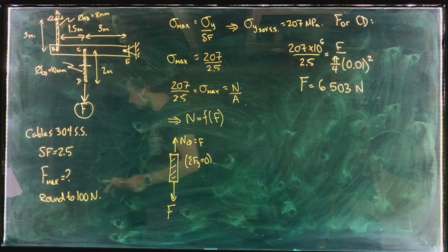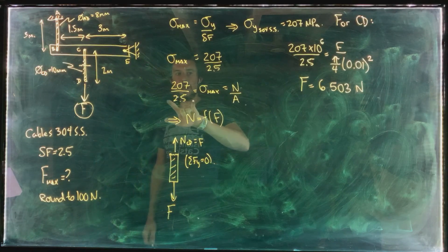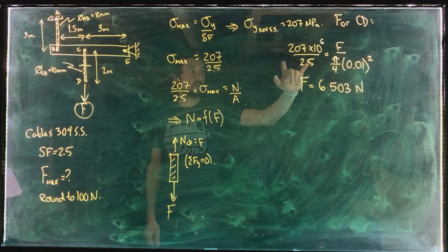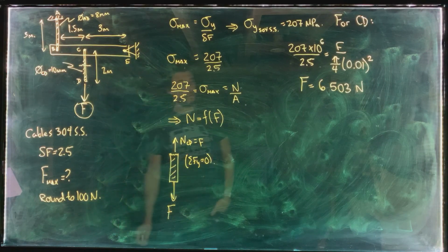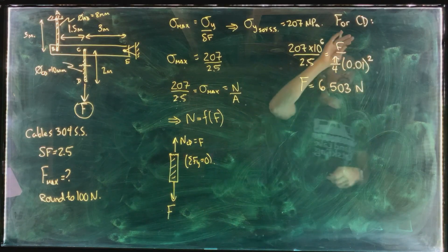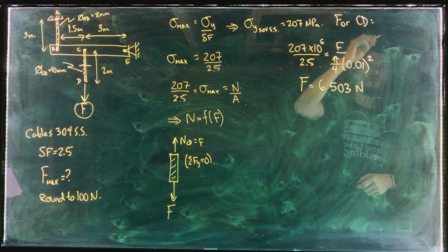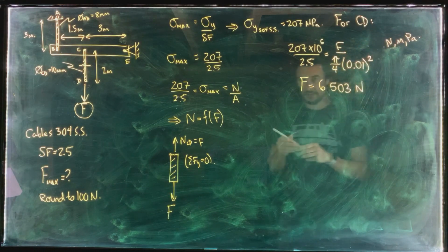Any questions up to this point here? Okay. Should 207 be converted to pascals? Yes, exactly. Yeah, so I did that. I wasn't doing that here, but yes, when you actually put in the numbers, you should do that. Okay. Everything, when you're working in metric and you've got equations involving stress, you want newtons, meters, pascals as your units there.